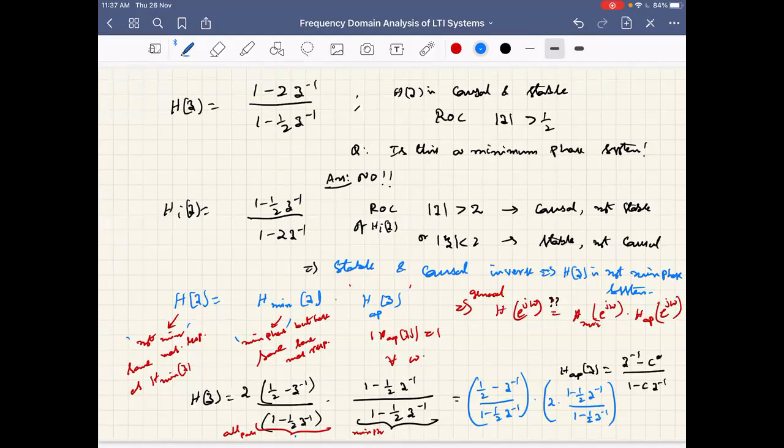Okay, so we have taken here a trivial example wherein the minimum phase all became 1 itself. Okay, numerator and denominator are same. Now let us take another example to demonstrate this. But the discussion here indicates that we can decompose any system into an all pass and minimum phase.